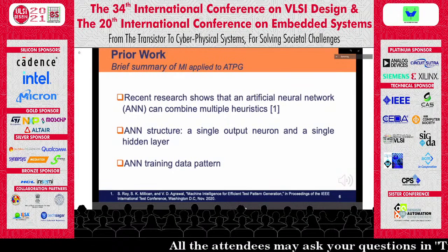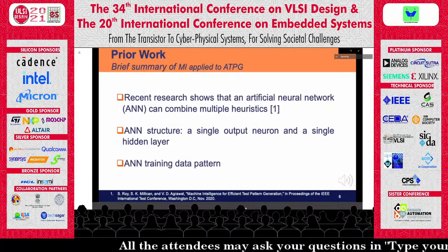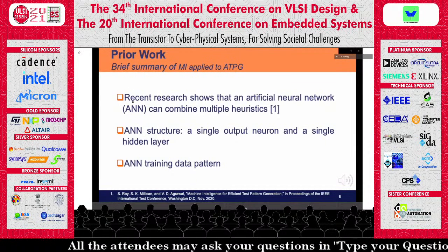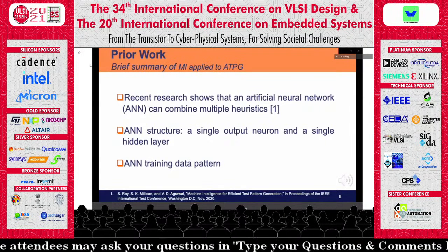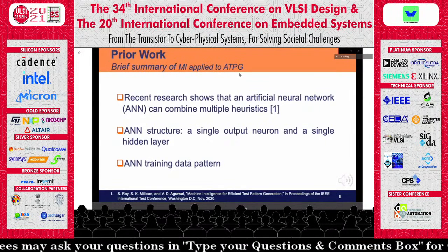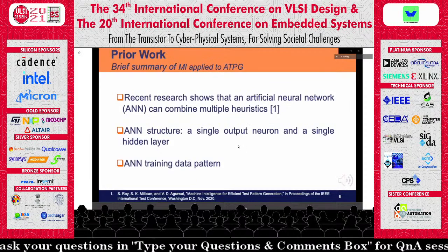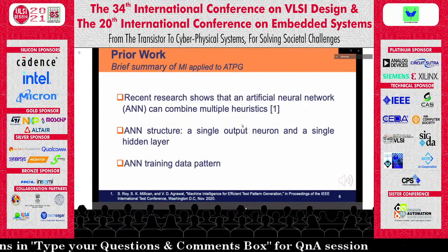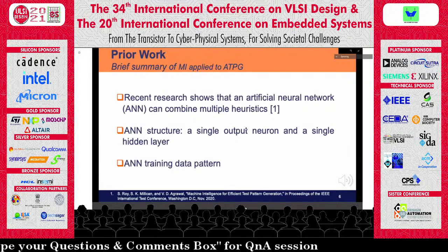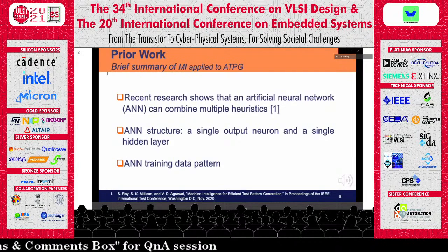Conventional PODEM ATPG applied to hard-to-detect and easily detectable faults in selected benchmark circuits provides training data for nodes, marked as success if the backtrace leads to a test, or failure if it results in a backtrack. Each entry in the training data pattern comprises the COP controllability, the circuit depth, and the driving gate type given as a one-hot string on the decision point.